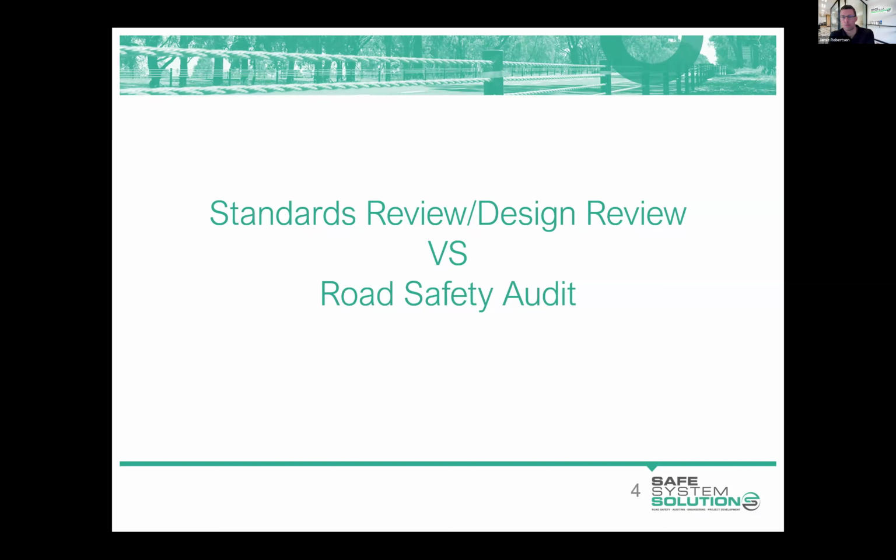So we need to put ourselves in the position of the different road users that are going to be using a piece of road or an intersection, and think about whether they would feel safe. So it's really important to get out there onto a site, think about how safe you would feel. And then a lot of these issues that you'll pick up do come back to standards, and you can quote a relevant standard to support a finding, but I encourage you not to think standards in the first instance when you're doing a road safety audit.